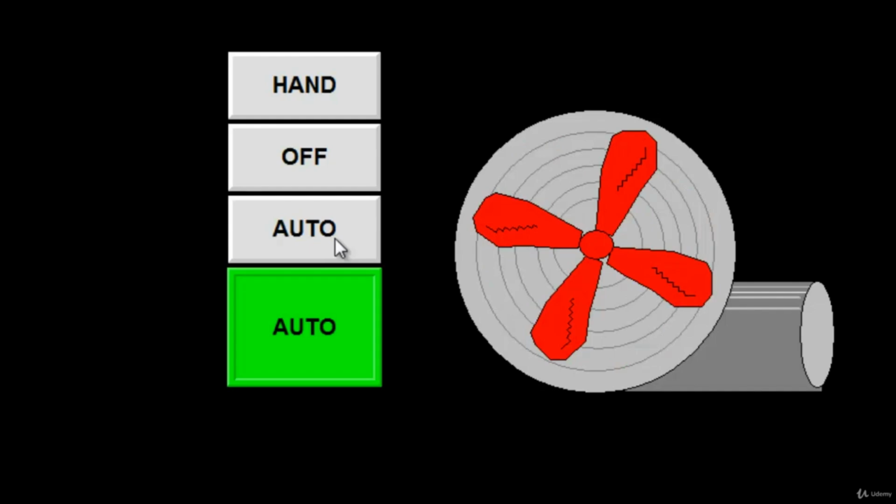Generally, in an actual HMI project, you can have 20, 30, or hundreds of alarms, but they all set up the same. Depending on the HMI project you're using, setting up the tags might be a little different, setting up the messages might be a little different, but those same basic components, alarm reset and silence, tags, and messages, are pretty standard in all HMI packages.